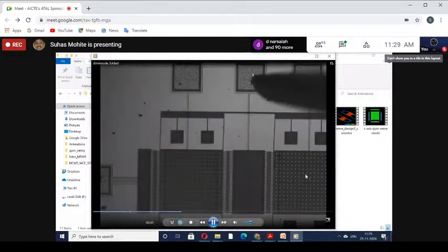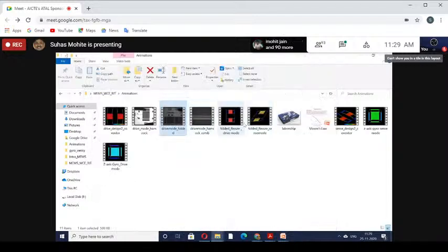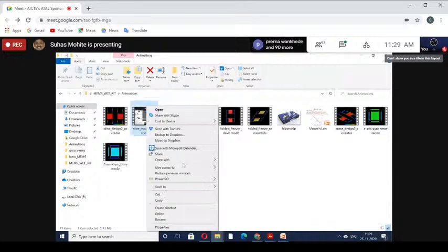There is another plate here. There is a reason why two masses are used: because of accidental handling or any other external acceleration, both these plates will experience the same acceleration. But since they are moving in and out, the change due to other effects will get cancelled, and that's why this twin pair of devices is used. So with one more small device presentation, I will close this in the next minute.